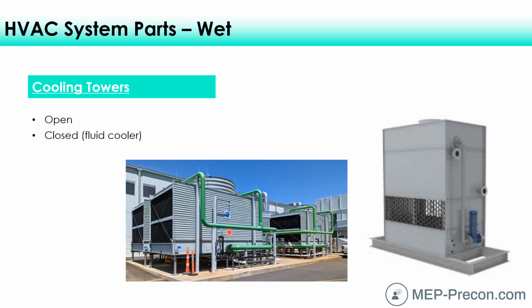If you build up a lot of scale, you can imagine if you build up a 1/16 of an inch or an 1/8 of an inch would be a whole lot. You'd never get that much, but even a 1/16 of an inch could dramatically increase your energy bills because it's just going to make your equipment work harder to get the same amount of heat transfer that it did when it was nice and clean.